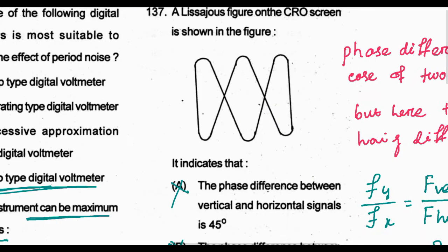If we draw a line here, and here we draw a line like this, this one is the y-axis, the vertical axis, and a vertical tangency is the Lissajous pattern touching the line. How many times it touches is called the number of tangencies with the vertical axis. Here it touches only once, because this is like a straight line, so this is 1.